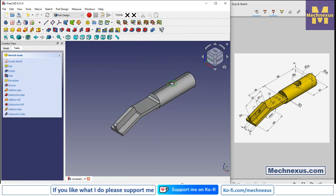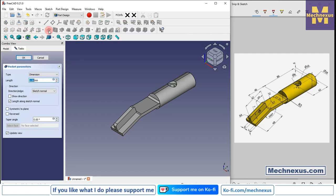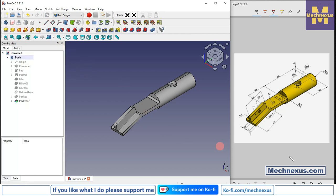Exit from the sketch. Now depth of this 16 mm diameter is of 6 mm. So we will select the sketch and click on the extrude and provide here the 6 mm. Click on OK.